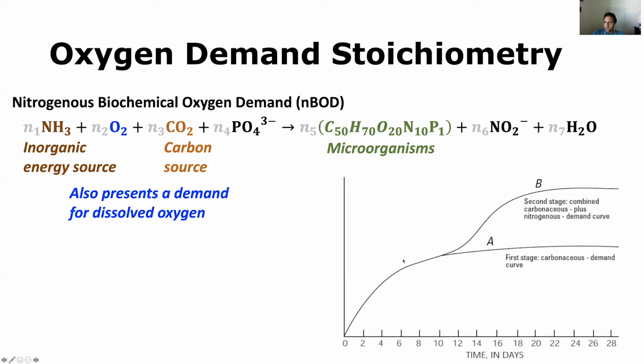Normally, with domestic sewage and the 5-day BOD test, this is not anything to be concerned about because the increase in the oxygen consumption associated with these microorganisms will typically happen after the BOD test has been completed, because these microorganisms grow a little bit slower. There's a little bit of a lag time before you start to actually see a measurable decrease in the dissolved oxygen concentration due to their microbial activity.